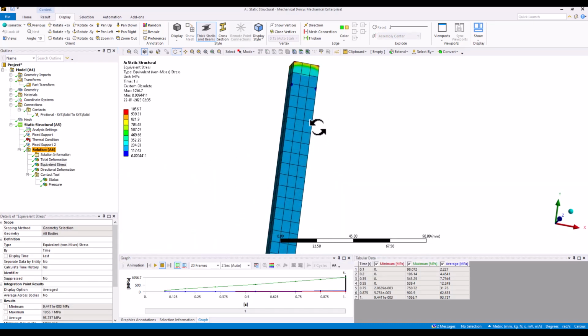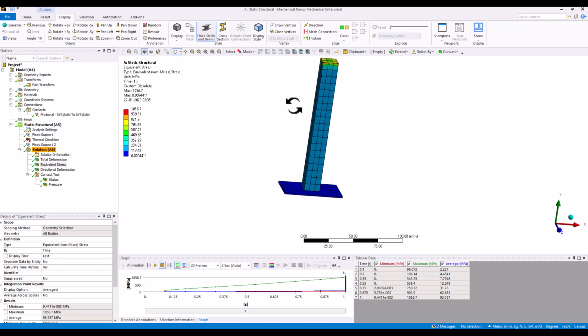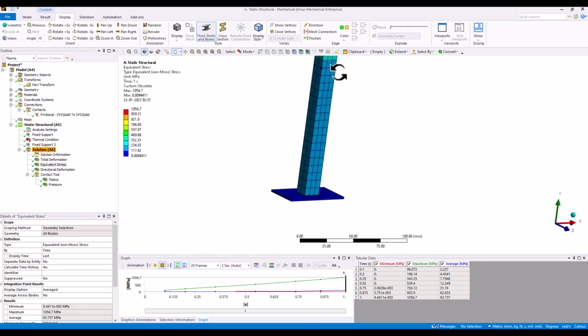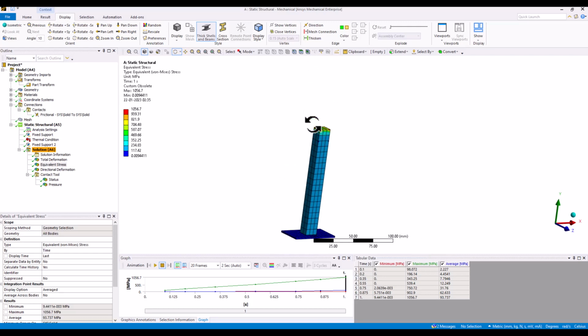But in this case, we can ignore this because our area of interest is to see how much stress is getting developed in this bar, and we can also see it is very localized. There are ways to remove this fictitious singularity. I will put some blogs or links in the description that discuss this in detail, and how you can avoid this stress singularity in this specific region.